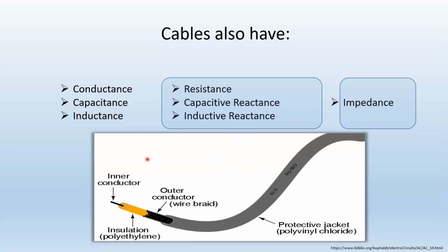All right, what is a capacitor? A capacitor is a couple of plates. There's one plate, and there's another plate, and there is a lead to each, and that's how things are. The bigger the plates, the more capacitance. The closer together the plates, the more capacitance, and so on. But the bigger the area of the plates, the more capacitance, which means the reactance is going to be changed, which means the impedance will also be affected.